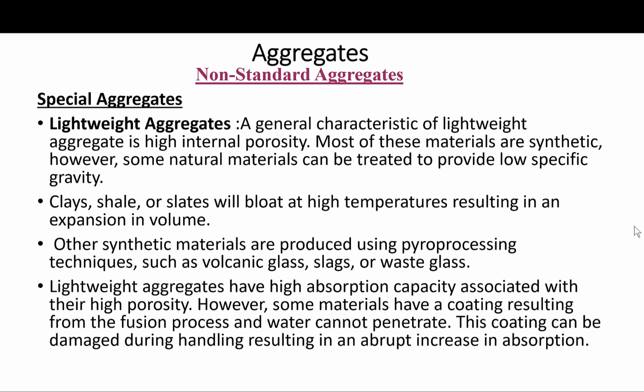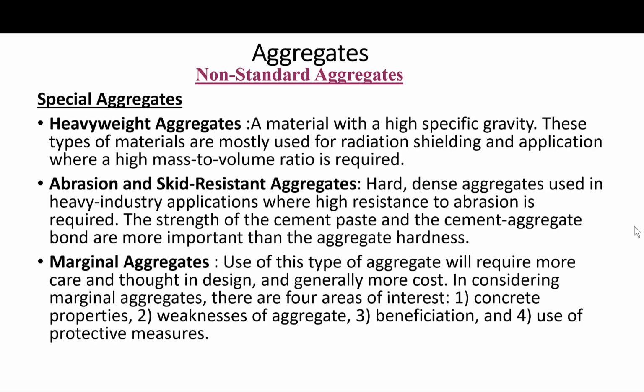The lightweight aggregates have high absorption capacity associated with their high porosity. But some materials have a coating resulting from the fusion process, and water cannot penetrate them. This coating can be damaged though during handling, resulting in an abrupt increase in absorption. And again, these special aggregates are used in special applications, and of course they are not used in structural concrete that will have to be of a certain strength and durability characteristics. So these are not fit for that use, just as a reminder.